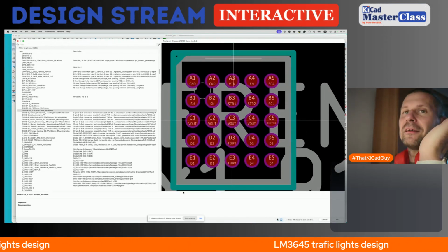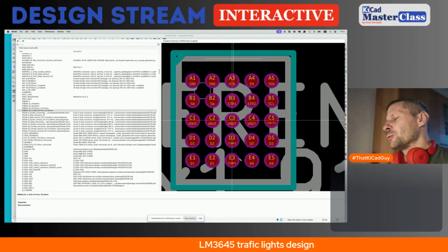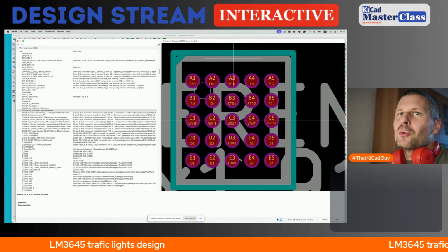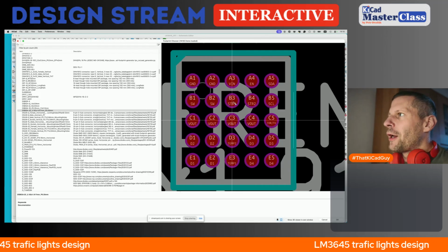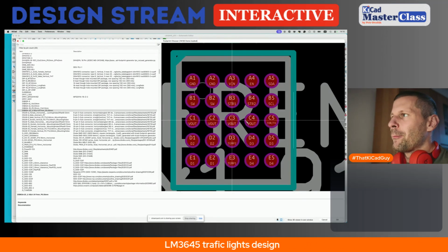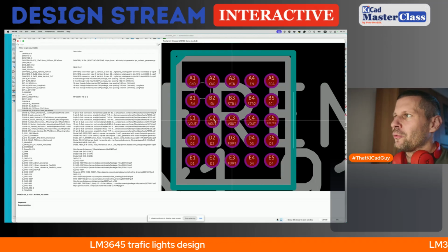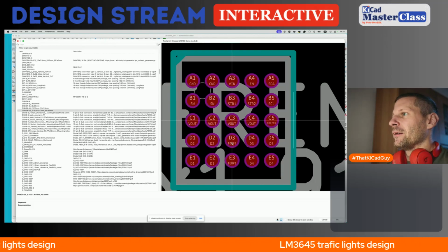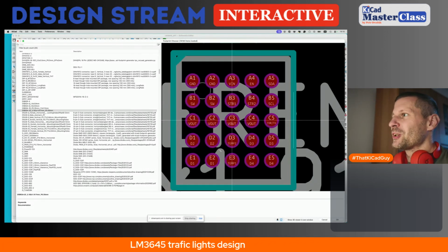Strobe 1, strobe 2, as you can see, I will zoom in because on your screen the picture is small. Yeah, I could open the footprint editor, but I'm not so smart. So strobe 1, strobe 2, and temp 2. These are the inner pads. You can see that V out will be fanned out by the track, switch as well, D2 as well, D3 as well. So only 3 pads.